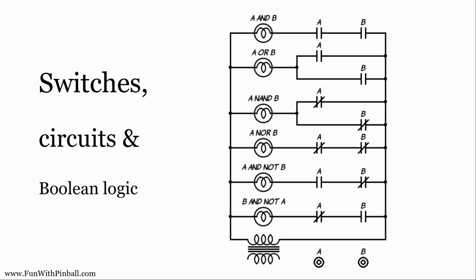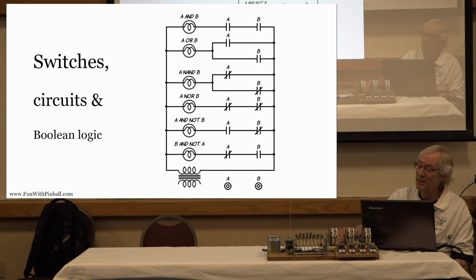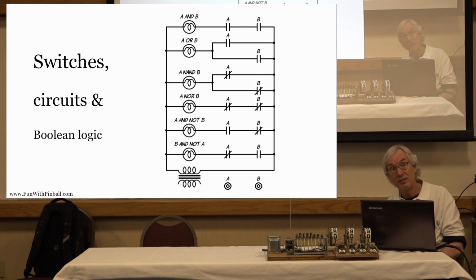So to get 10 points, right, there's a switch behind a target, and that fires a relay, and the relay fires a score reel. Well, initial observation is I don't get 10 points, right? Well, at a high level, there are 2 circuits there. So just by knowing which relay is supposed to fire, I can observe without touching anything. I can just observe, hit a 10-point target and see, does that relay fire, right?